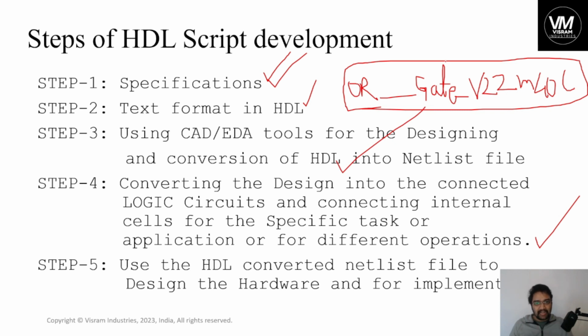Until you define the netlist, which means the technology or the type of cells that you need to use on the hardware, your HDL language is of no use. So keep this in mind, guys: whatever HDL language you write, it should be synthesized to the netlist level. Netlist is nothing but what wires should be connected. There are different types of wires with different widths.